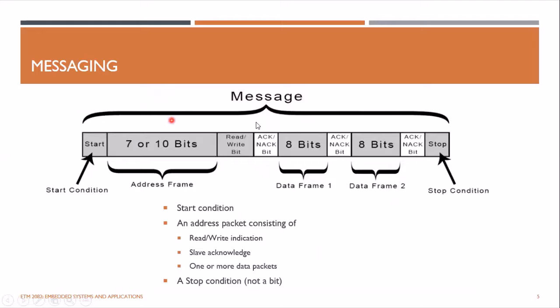Right. So this is the message format that the video has just explained. First, the start condition, and you have the slave address, the read and write command, and the acknowledgement by the slave, and 8-bit data. If you are just getting the data from the slave without having an address, you can have this. If you want to ask from a particular address, this could be the internal address of the slave. Otherwise, this could be data coming from the slave. And finally, we have this stop condition.